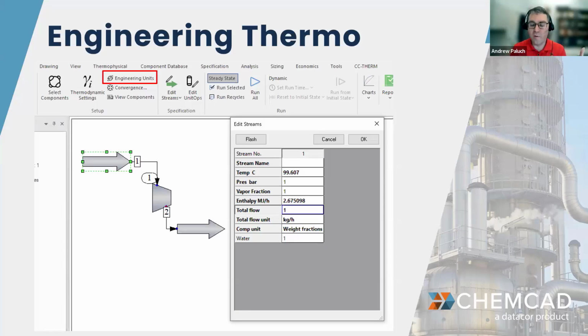But what's interesting is that when we go over to CHEMCAD and set these processes up, there are no steam tables. Well, what is CHEMCAD doing? It makes this connection to equations of state. So we can have a conversation about how CHEMCAD is calculating all of the properties of interest that I need via an equation of state, and not making use of the steam tables. It's useful and helpful so that students see how, in the real world, these calculations are done devoid of steam tables. We can make the connections to steam tables, how equations of state are used to generate those, and their value.